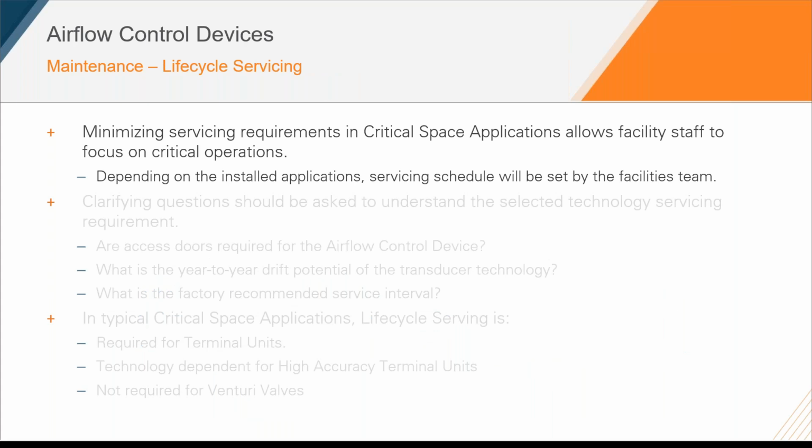So the last consideration we're going to talk about here before opening the floor to some questions is the life cycle servicing. This is a very complex topic, and selecting an air valve technology purely based off of cost can actually have some knock-on effects due to potential higher maintenance costs over the life cycle of that air valve.